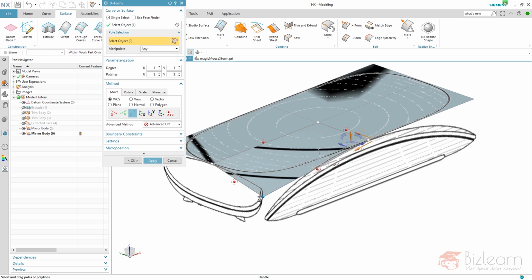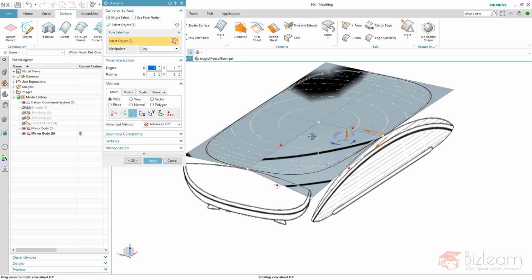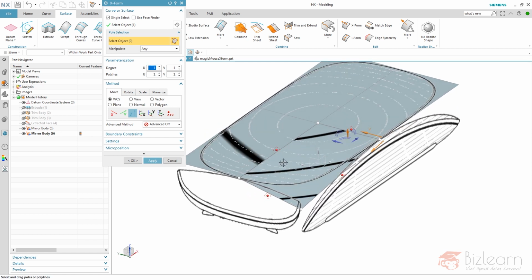And if I move this one, I'm no more tangent in that area. And you can see it by having a look at the reflection, because if a reflection is no more smooth and you have gaps between your reflection lines, this will tell you that we're no more tangent, we have an angle between. By Control and Z, you can undo an operation.